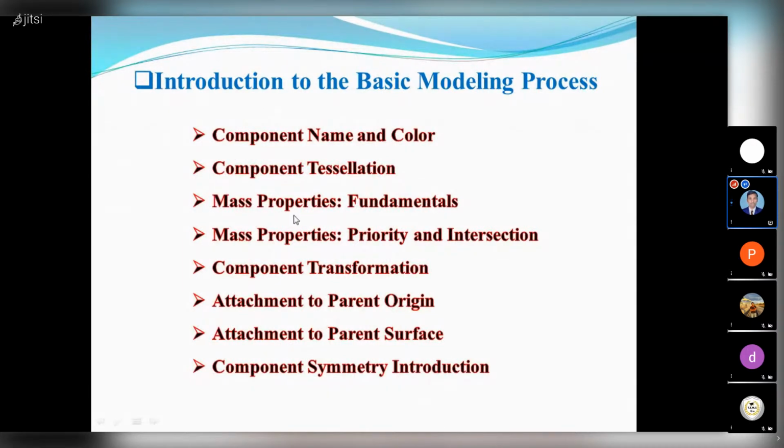Mass property fundamentals: I also showed how you can add your density and parameters. And component transformation: here we saw how we can move our component from one location to another. We use the x, y, and z axes to translate our component along x, y, and z. We also have x rotation, y rotation, and z rotation, by which we rotate our component.